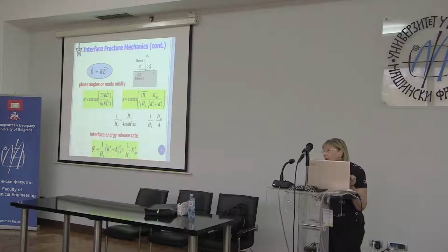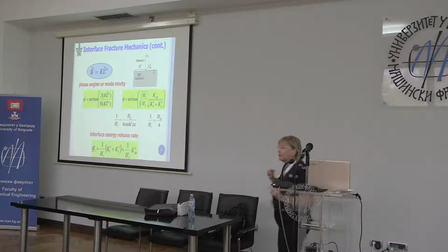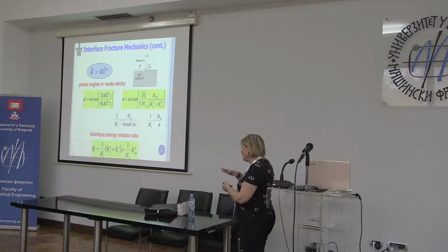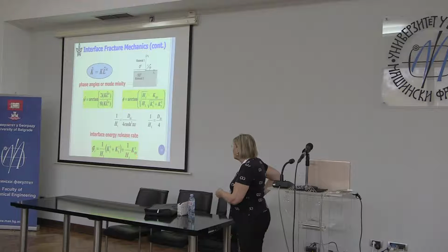We have one paper where we had 5 stress intensity factors, so we learned about it. At first we looked at it, and in fact, for the plus 45, minus 45, K1 and K3, I'll go into this when I get there, K3 turns out to be multiplying the square root oscillatory parameter, and then we have K2 that's multiplying the square root singularity.